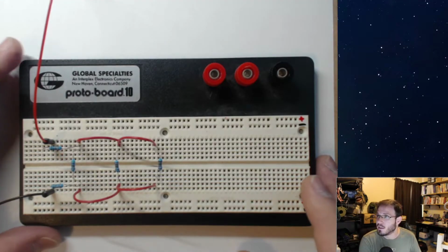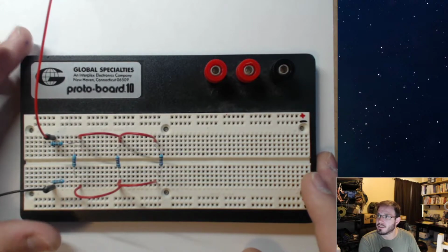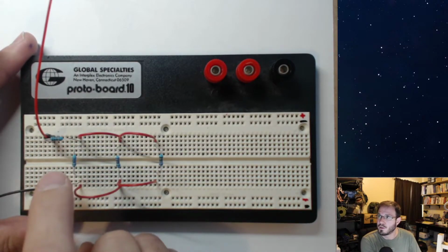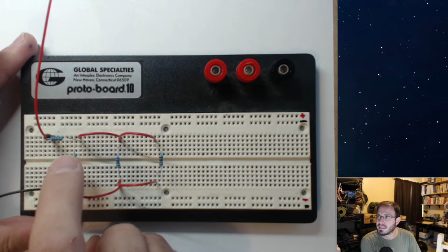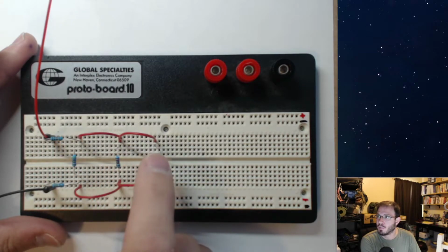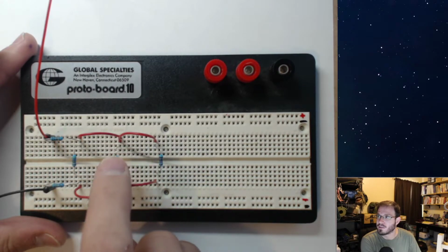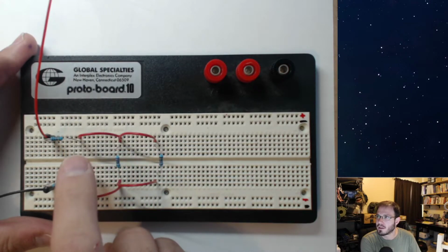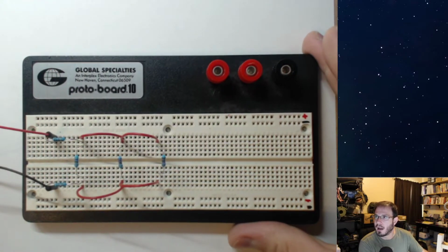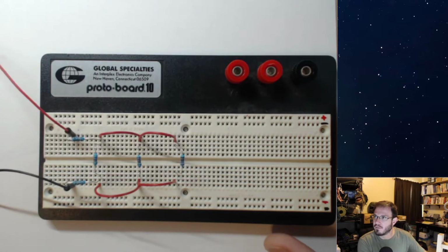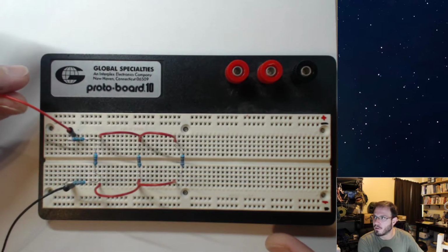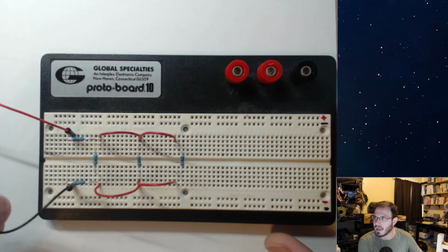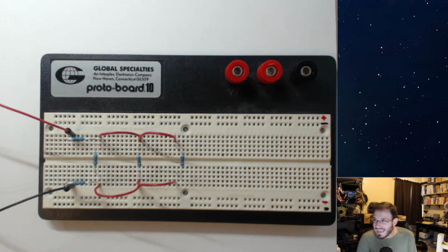Here, we can see the breadboarded version of this circuit. Okay, so I have those two 1Ks, the 4.7Ks, and then the 2.2Ks over here. All three of these are in parallel, and then my voltage applied is going to come in from these two wires, my red for the positive and my minus side of my 9-volt source coming from the black wire. Okay, so we need to get 9 volts applied to this circuit.